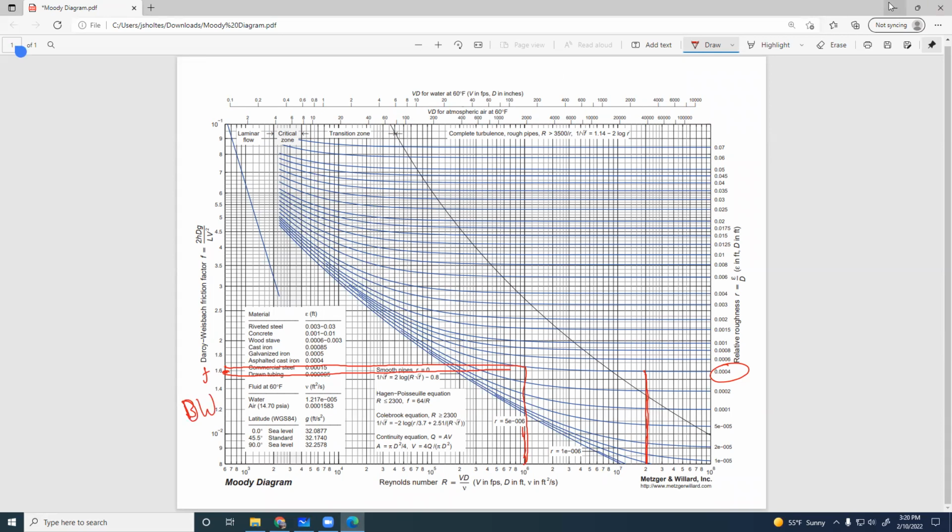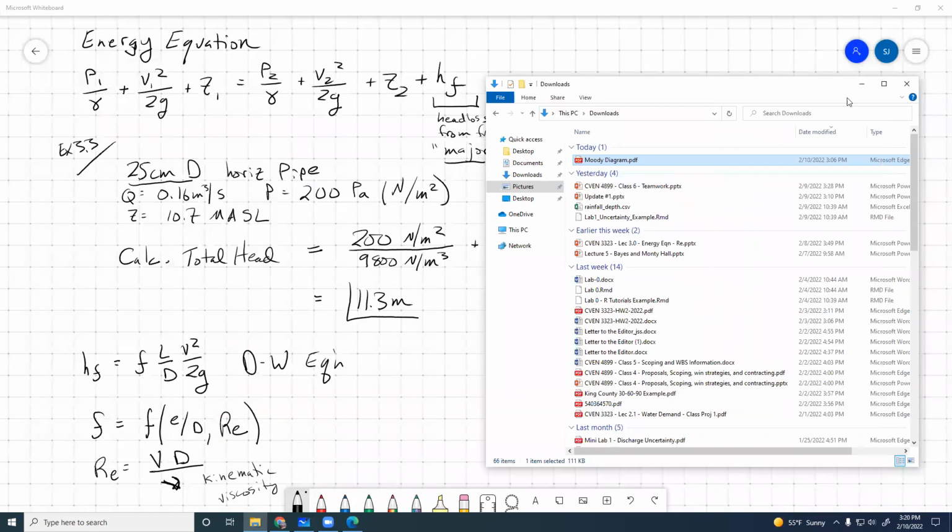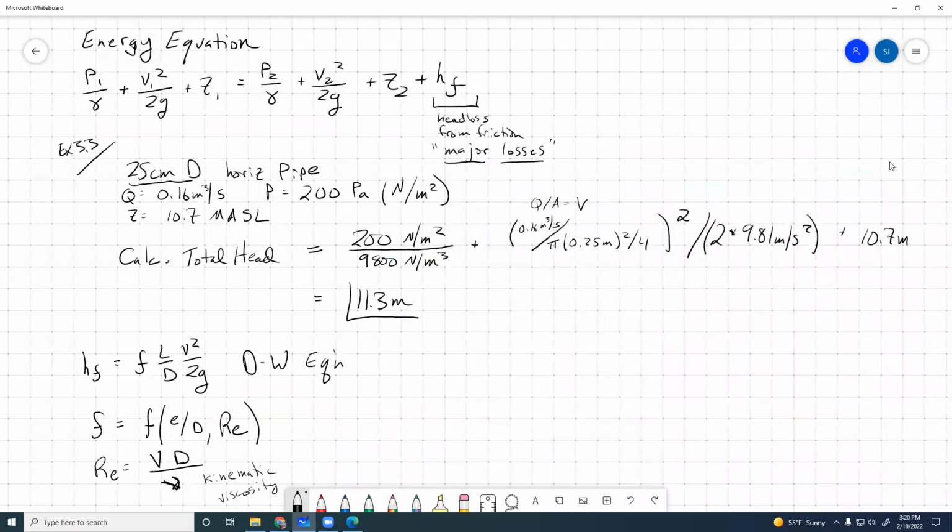So this is the friction factor that we would use to plug into the Darcy-Weisbach equation. We also introduced the Swamee-Jain equation. I won't write it out here again, but this essentially replaces the Moody diagram. It's kind of a bear to put in your calculator, but we can use it to calculate the friction factor. All it says is you need to know the relative roughness and the Reynolds number. You plug those values in and you calculate that friction factor value directly.